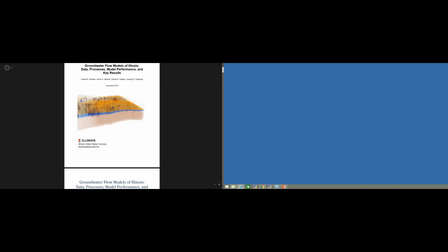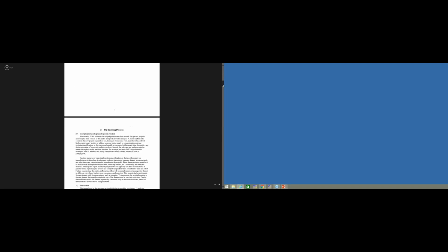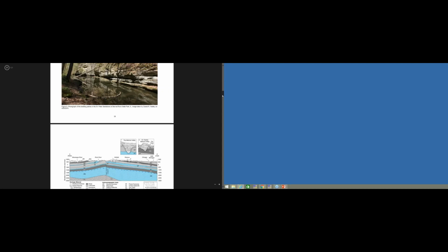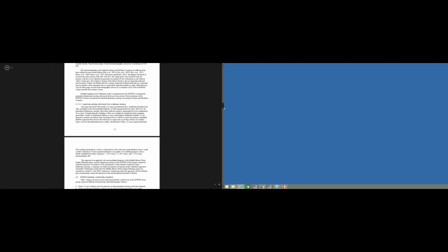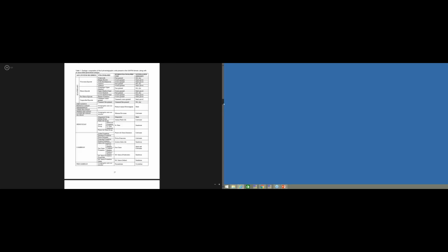And you're thinking the way to do that is with the float system you're describing, kind of a physical setup? Yeah, I would think so, rather than some sort of telemetry-based setup. I think it would be a little bit better as far as maintenance goes. If you put a float in and something goes wrong, Pete can yank that pump and figure out what's wrong with the float.